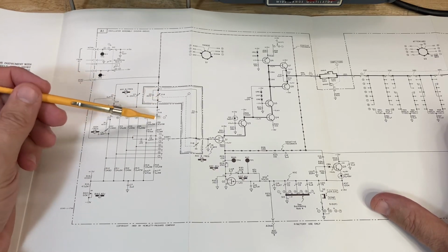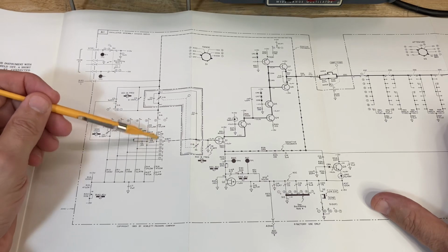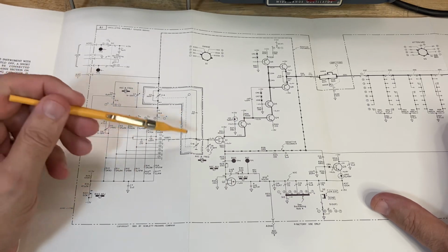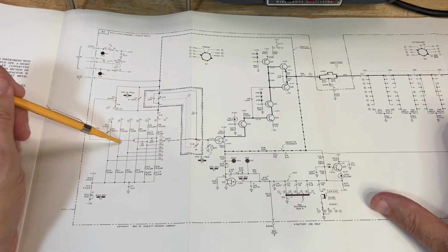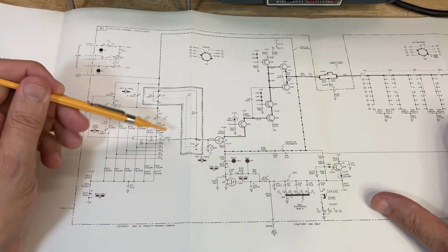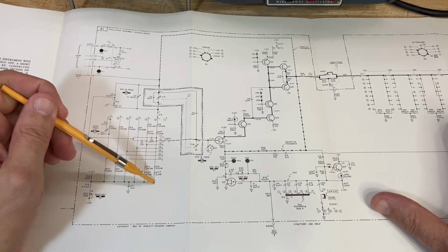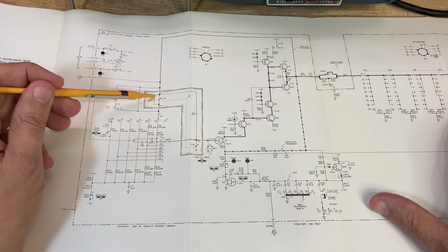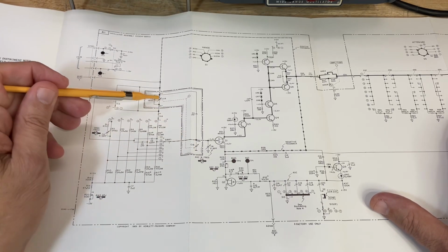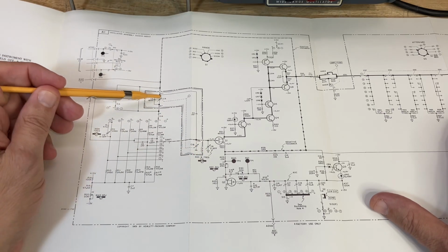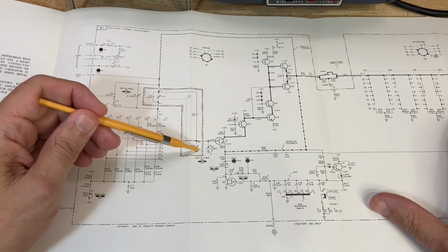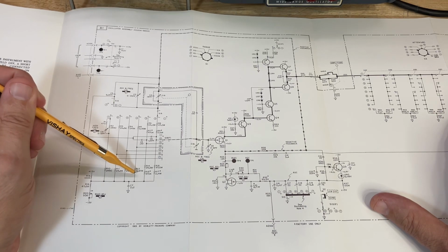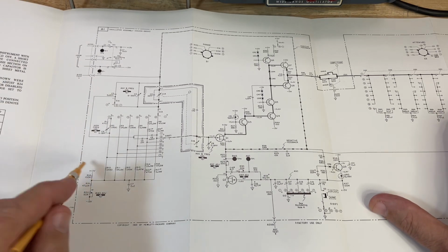Here we have the series leg of the Wien bridge with one tuning capacitor and a fixed resistor for each range of frequency. And here we have the parallel leg of the Wien bridge, where here's the tuning capacitor in parallel with a fixed resistor. The 204C does not use three gangs of tuning capacitor. It only uses two gangs of tuning capacitor. So the value of this capacitance is exactly the same as the value of this capacitance, which implies that the value of this resistance should be exactly the same as the value of this resistance. And in fact, it is for each frequency range.